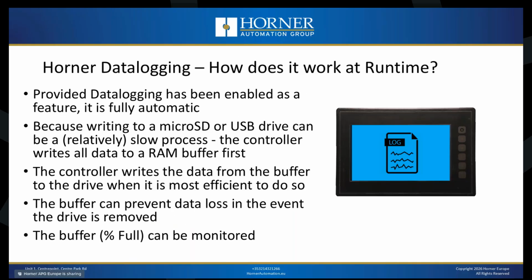How does data logging work at runtime? Provided data logging has been enabled, it is fully automatic. Because writing to a micro SD or USB drive directly can be a relatively slow process, the controller first writes all data to a RAM buffer. The controller then writes the data from the buffer to the drive when it is most efficient to do so. This buffer can prevent data loss in the event the drive is removed. The buffer full percentage can be monitored as well.